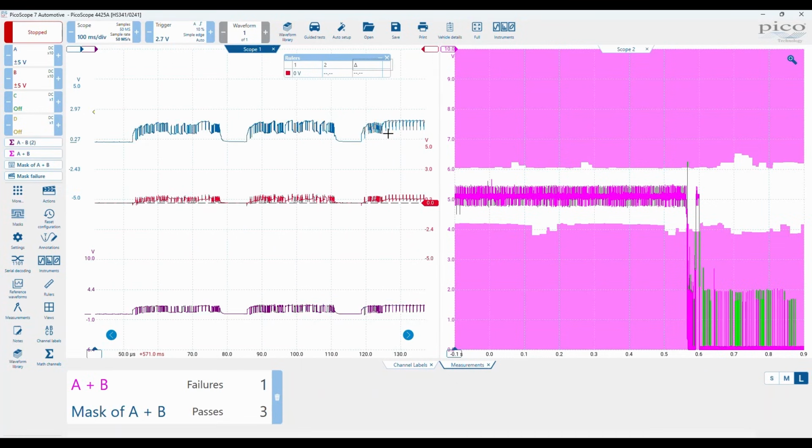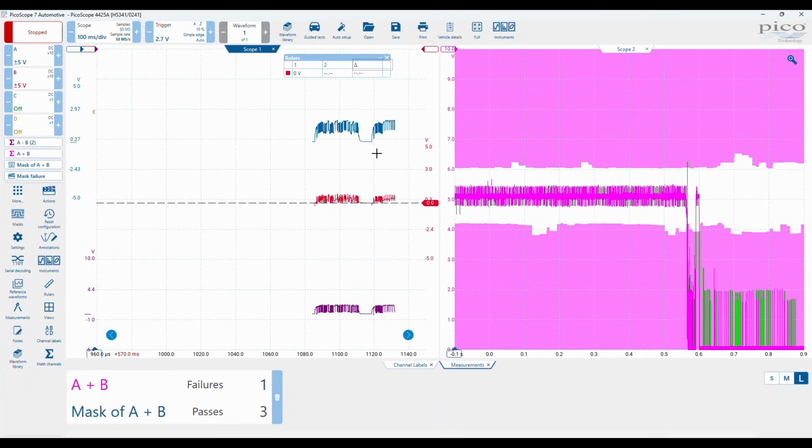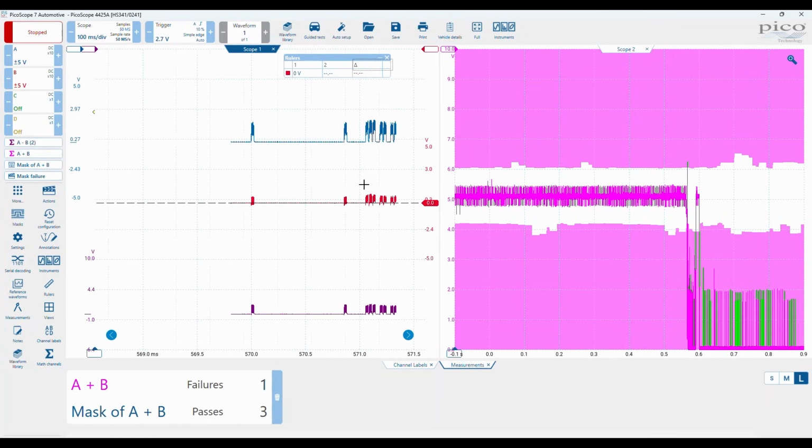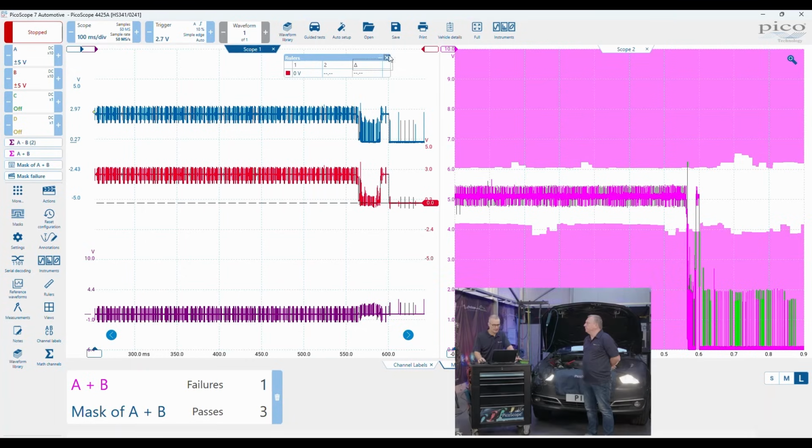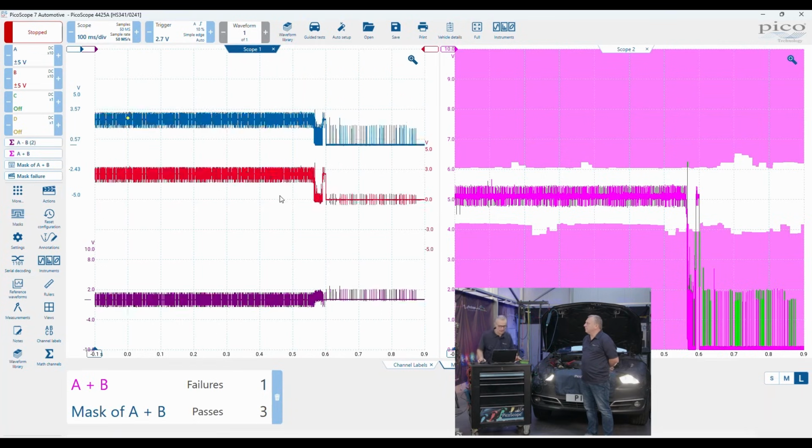Yeah. And that shows the fault tolerance and the robustness of these twisted pair networks. We saw this with shorting, was it CAN low, down to ground in the previous video. The CAN high still tried to maintain communication and did so successfully as well.